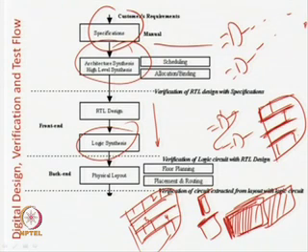CAD tools are available which can help you in doing this physical layout. Once the gate level connectivity information is given by logic synthesis, in the physical layout we place these gates in the die in this way and do the interconnection, because if this point has to be connected to this point, you have to route it without any kind of shorts and all those things. So, the physical layout procedure will put all the gates in the die so that minimum area is taken, and it will also route the pins and the connections between the gates. That is actually done in physical design.